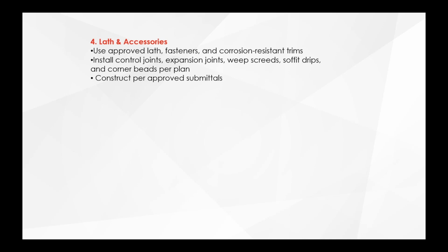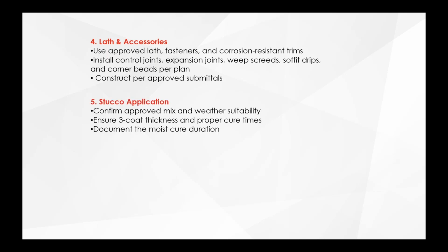You could also, with the lath and accessories, make sure that you're constructing it per approved submittals. Like I said earlier, there's so many different manufacturers out there. What if you're building on the coast and you got to use zinc or vinyl or an upgraded galvanized coating? You want to make sure whatever's being called out is what you're specifying based on your location.